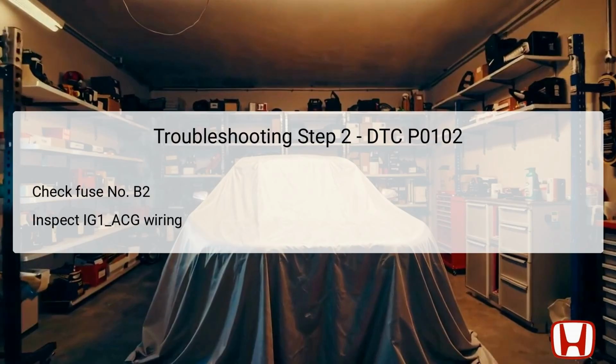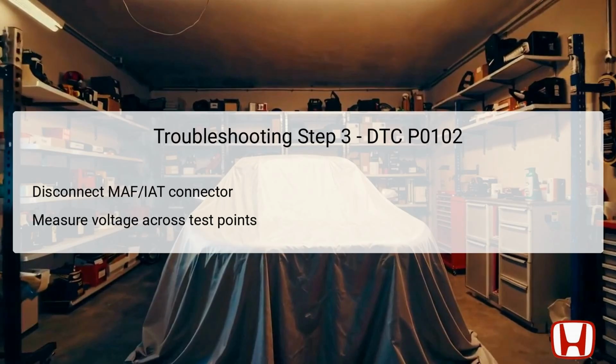If the fuse is intact, it indicates that the IG1 ACG, Ignition 1 Accessory Ground, and IG1 FM, Ignition 1 Airflow Meter, wires are likely not shorted, allowing you to proceed to the next step. However, if the fuse is blown, this indicates a short circuit in the wiring between the MAF, IAT sensors, and the fuse, which would require you to repair the wire short, replace the blown fuse, and verify the repairs before moving forward.